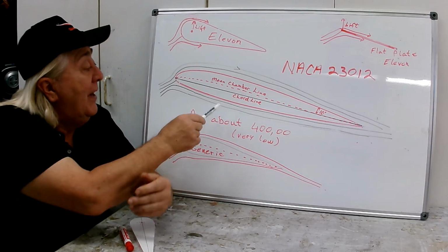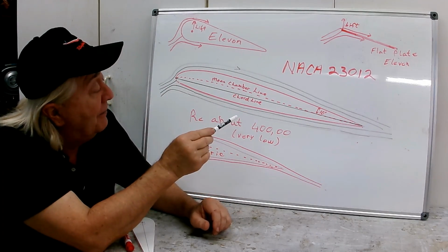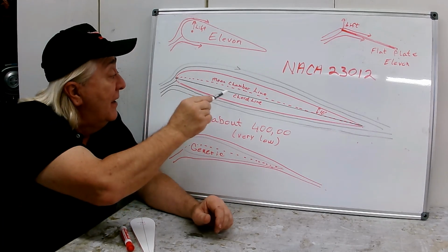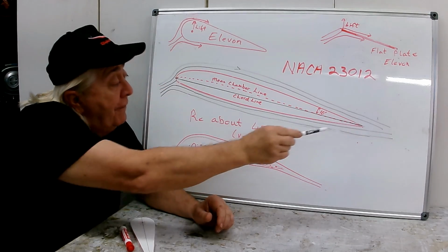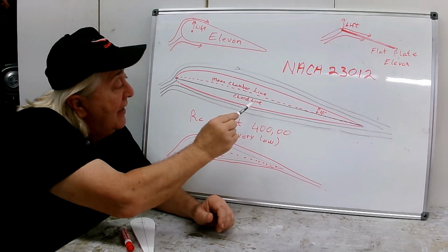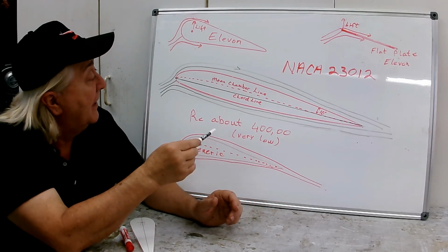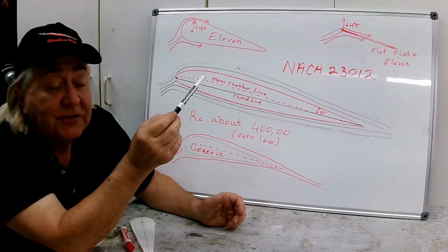So here, the red outline is my airfoil near my wingtip. And just if you're not familiar with this kind of stuff, the line from the furthest point forward to the furthest point aft, this black straight line, is called the chord line. It's the length of the airfoil, the characteristic length. The dashed line up here I've labeled the mean camber line, and that's what that is.